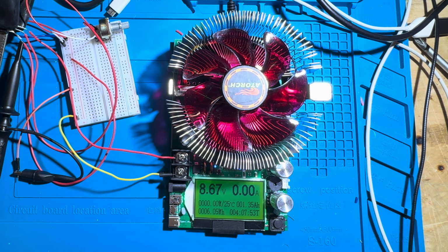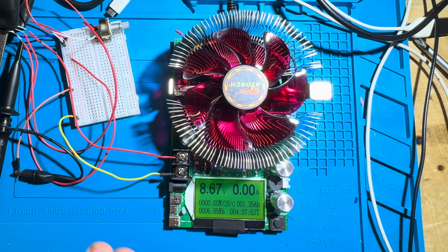Now, one of the issues we're having here is this MOSFET is not fully open. If it were fully open, you would see 0 voltage across the MOSFET, and we'd see 12 volts here. But we can't get that. The gate voltage actually needs to go a couple volts higher than the drain to source voltage on the MOSFET, and we don't have that situation here.